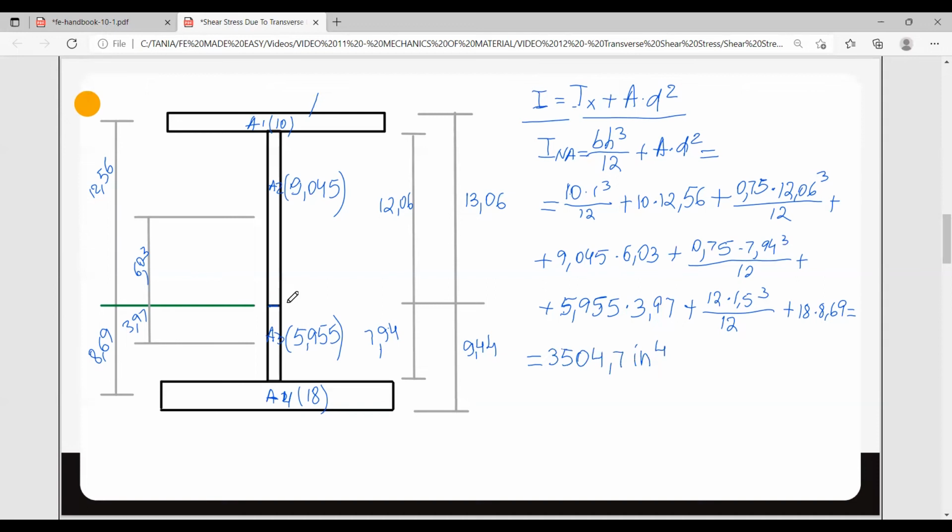This neutral axis here divides this shape into 2 other shapes, and the moment of area of these 2 shapes is the same, meaning that in moving forward, you can calculate the moment of area of this shape or the moment of area of this shape to use in your calculations. I would like to calculate both, and I would like to show how they are equal.